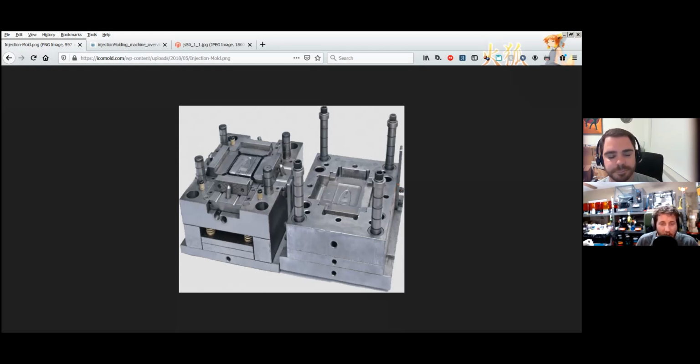But when you're talking hardcore production, you don't necessarily have that option. So these slides are really useful. And if we look at, I'm going to bring up for the people watching us a commercially available silicone sock that is for an E3D Volcano. It has little clips on the top that are definitely made with a slide. So there is a core, and that core likely has those cutouts so it can fit.